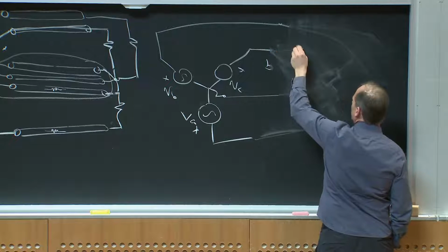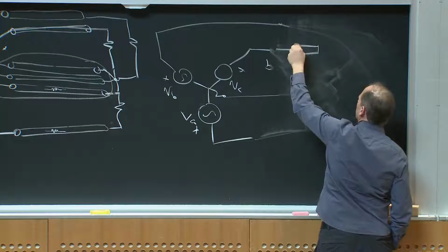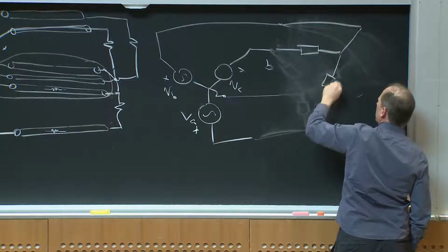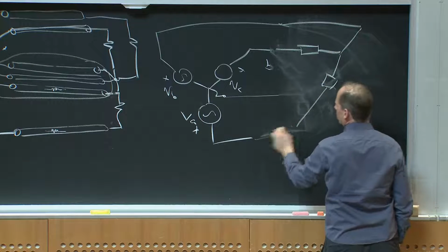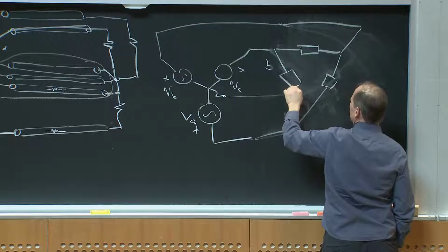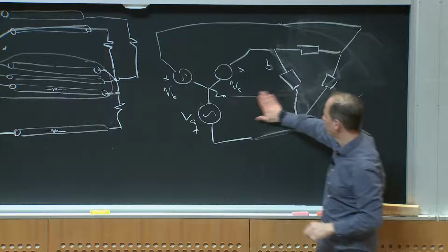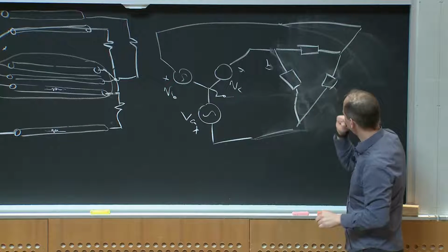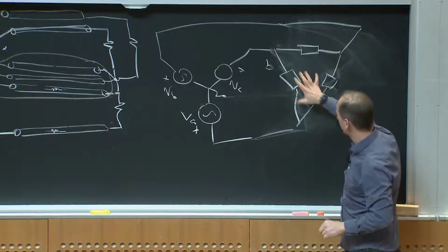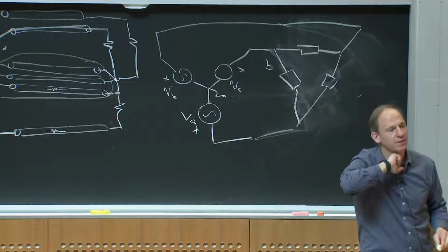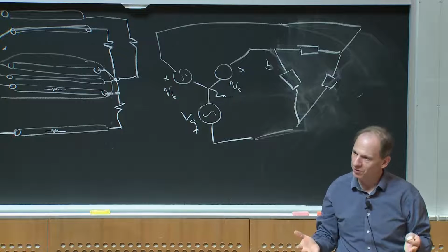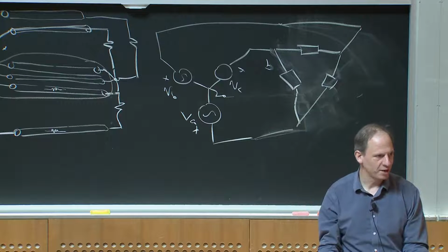Suppose I connect up, I have some load here, and then I connect another load here, okay, and then the last load here. Okay, so there's no neutral point connection in this thing, okay, and if I looked at these things, now these could be resistors, in which case everything's simple, but if I'm going to start to create rectifiers or other elements, just because my voltages are sine waves doesn't mean my currents are sine waves.